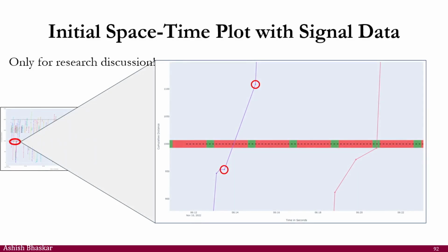So, these are the points you have observed. Obviously, this one might not be a split failure, because it looks like it is hitting during the green time, but red time. You have to consider the actual profile based on the shock wave or other aspects, because there might be a shock in the system, so do not blindly use it. For your trajectories you really need a good number of samples, and you also need more frequent observations. That is your requirement.